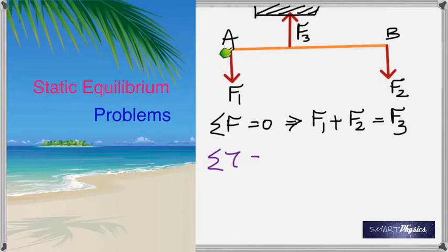With this point in perspective, F2 is still going to be clockwise, but it's going to be F2 times, help me out, AB. And what's the counterclockwise? F3. You see, F3 is the one that's trying to rotate it counterclockwise, and that would be F3 times AC. What about F1? It does not have any torque at A. Reason? The distance is 0.